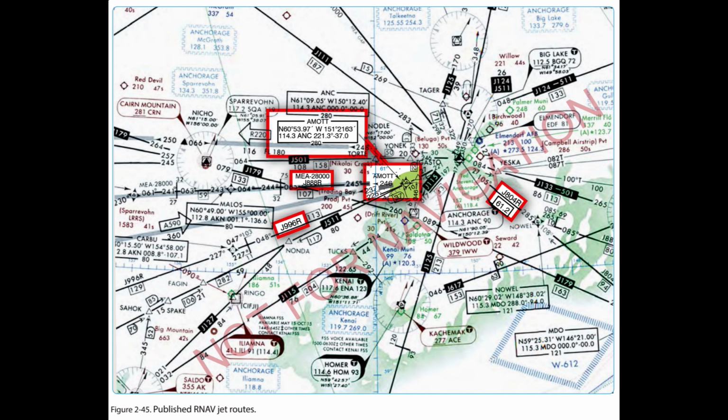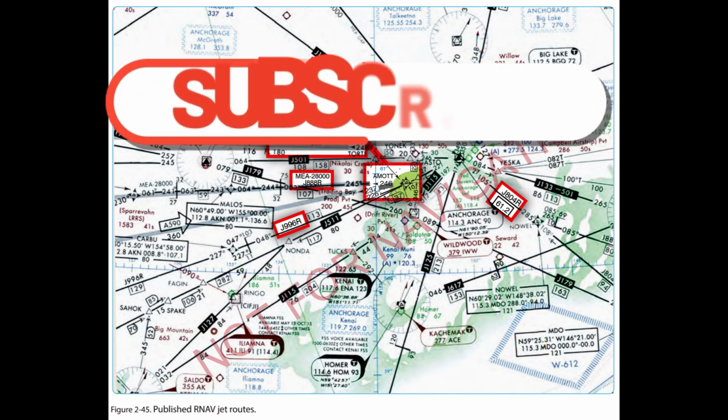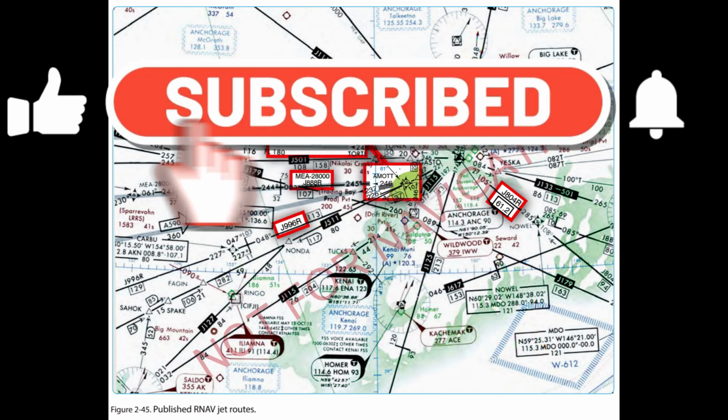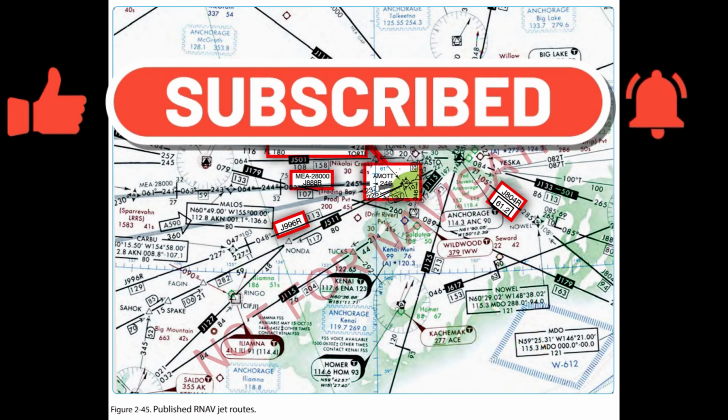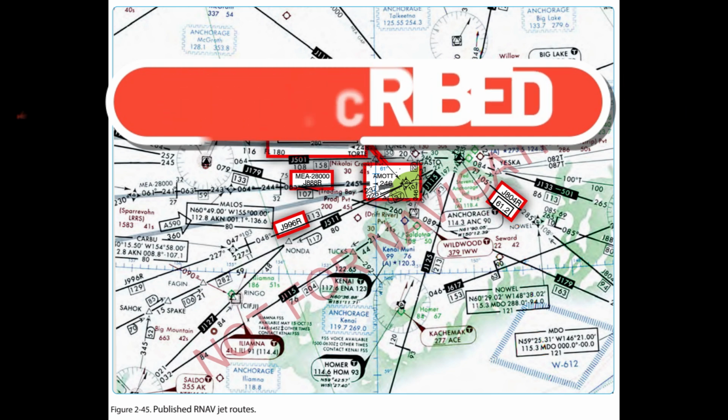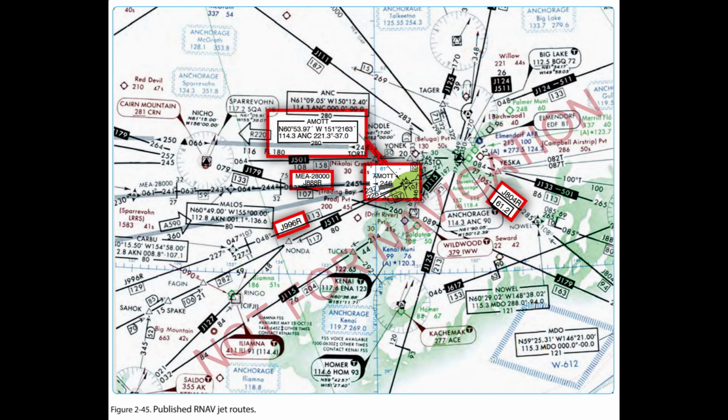3. Plan the random route portion of the flight to begin and end over published departures/arrival transition fixes or appropriate nav aids for airports without published transition procedures. The use of preferred departure and arrival routes, such as DP and STAR where established, is recommended.